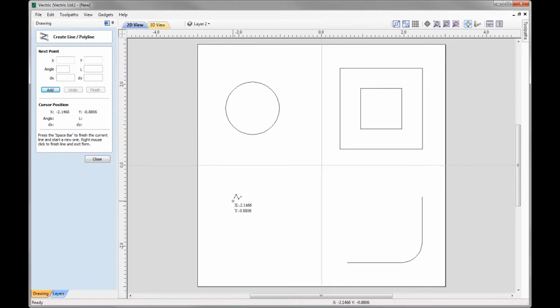So let's have a look at the shape in the lower right hand corner. So I'm just going to run my cursor over that to wake it up. And then I'm going to move the cursor away, and I'm just going to randomly move that around, and you'll see now that we're displayed with a blue line running vertically through the center of the object. So when you see a blue line, that's the software's way of telling you you've found an object bound. In this case, we've found the center vertical line for the object that we've woken up.